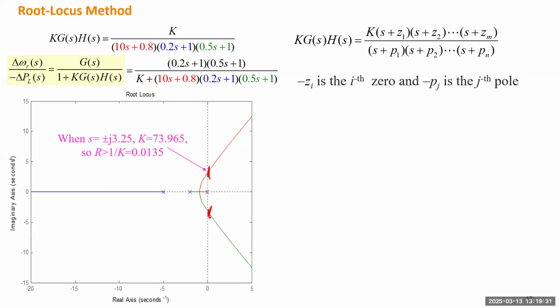But this basically explains that the open loop transfer function has a number of poles and a number of zeros. When you generate this closed loop transfer function, those poles will be here, right? Those zeros will be multiplied by k and put on this side. So when k increases from 0 to infinite, first this one plays a dominant role in determining where the poles are.